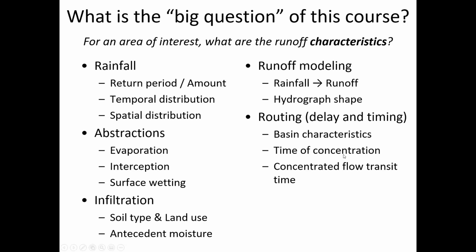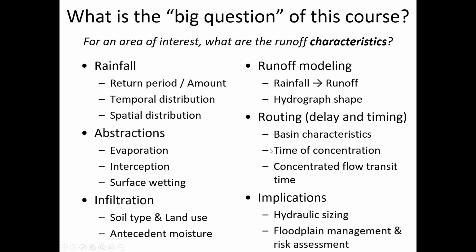So the time of concentration, not just for surface flow, but also as the water is going through the streams that may form. So the delay of the hydrograph as it travels through the watershed is part of what we'll calculate in those computerized models.